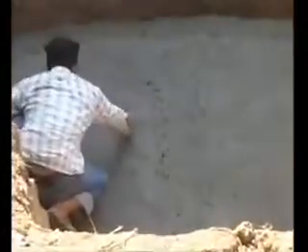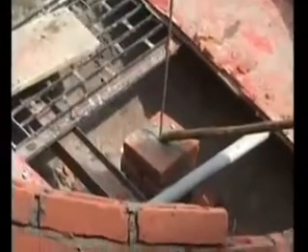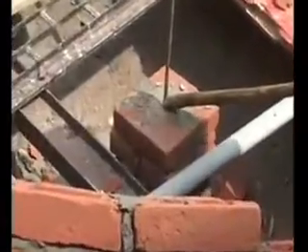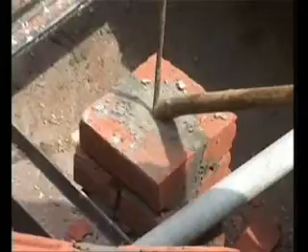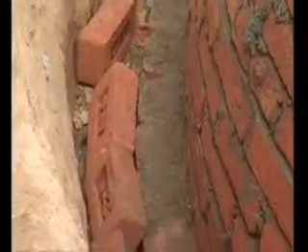After completion of the foundation, we start the construction of the upper part of the Deen Bandhu biogas plant. For the construction of the upper part of the plant, we fix a wooden stick at the center for measuring the actual radius of the digester. The first layer of bricks is laid on the foundation of the digester, which is 9 inches thick.